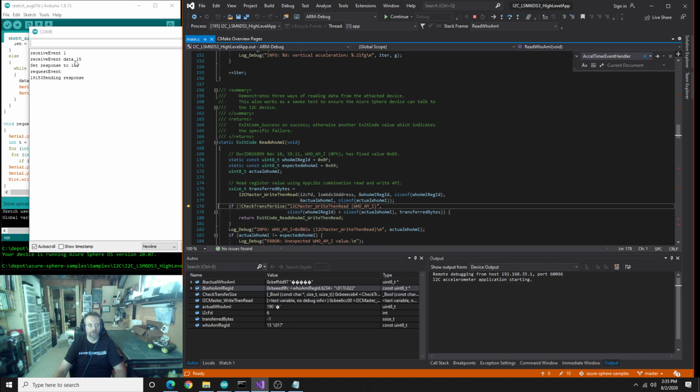I mean, it transferred this 1 byte of 0f onto the bus, and we set a response, but we took too long, and so it timed out. And the actual who am I does not match the expected.